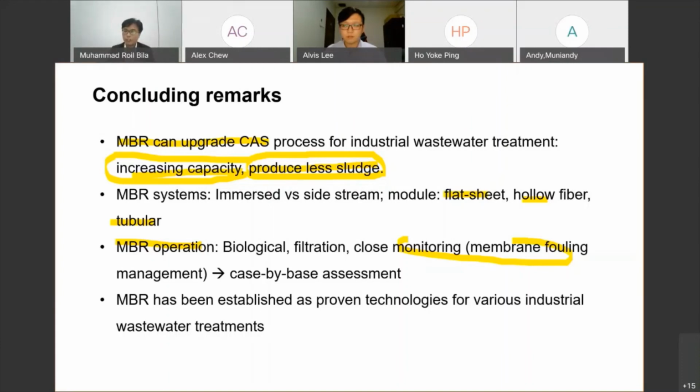So instead of dealing with floc, you are dealing with a smaller floc. Another indication if the problem persists is that your microbes will become cannibals, endogenous respiration. They will eat others. This is what happens when you have a too low food to microorganism ratio. The implication for the quality is almost nothing. It is just that probably your floc dynamic will change a bit until you restore the condition to the normal design.